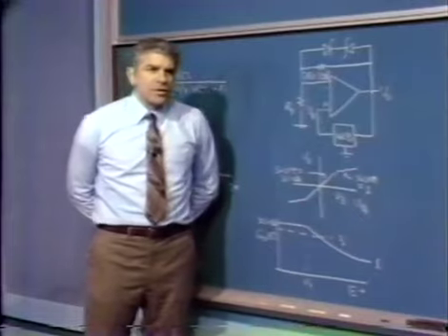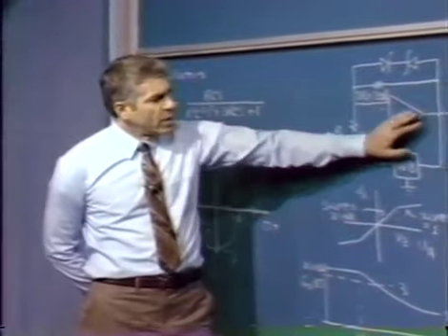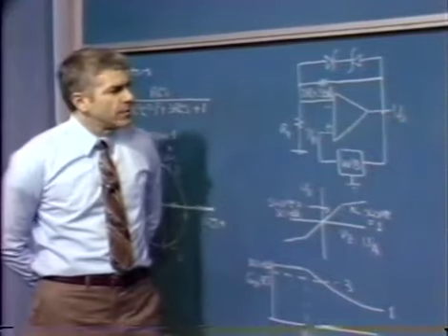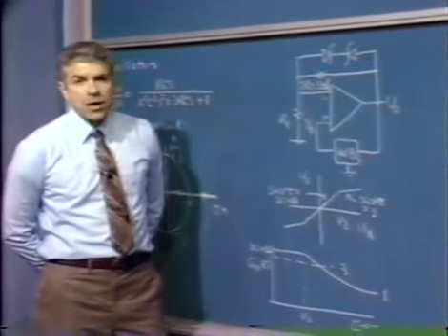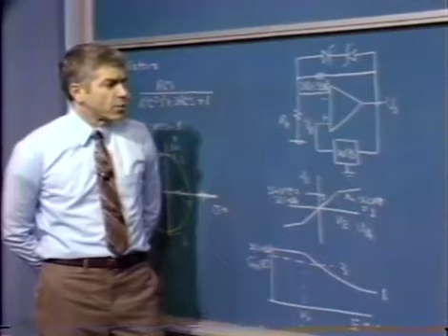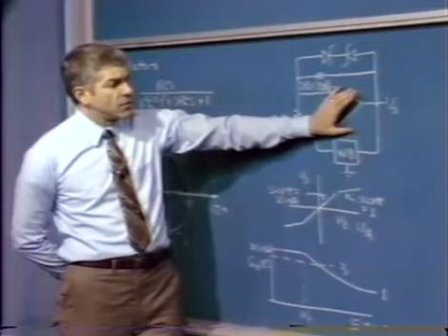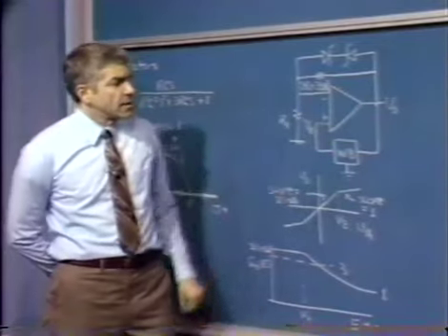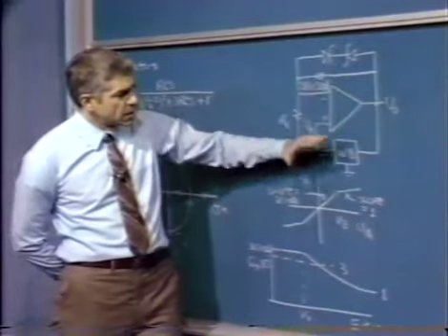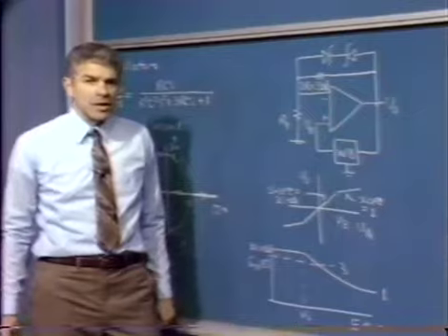The difficulty with doing that is that we get harmonic distortion, certainly. We would typically, in this situation, like to use the signal Vout as the output voltage of our system. Because it's buffered, it comes from an operational amplifier. That'd be a nice point to use as an output for the overall oscillator. But that signal has harmonic distortion, and in fact, the harmonic distortion is unattenuated by the frequency selective network in this case. Because we apply the input to the amplifier here, the nonlinearity occurs in the amplifier, so it really squeezes down the top and bottom of the sine waves. We get some harmonic distortion out of that.